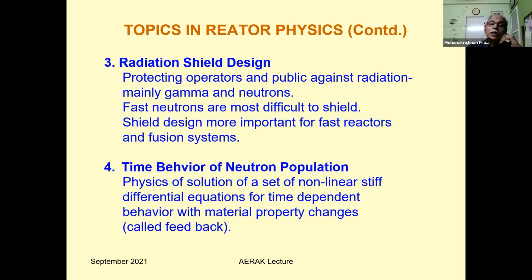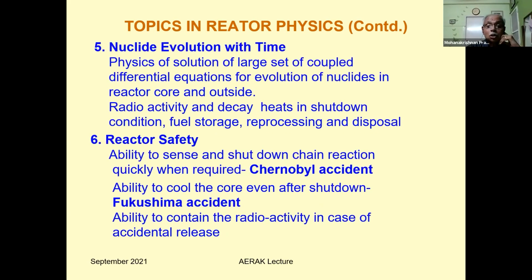Nuclear evolution with time. That is, when you want to operate the reactor, the fuel is burning, so you have to keep track of that. And when you are putting it outside the core, it is cooling and decaying. You have to keep track of that. So this radioactive decay, their decay amounts, heat generated, all these are to be solved. So this is nuclear evolution with time.